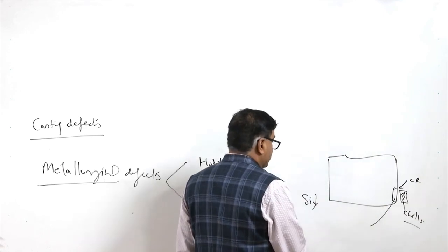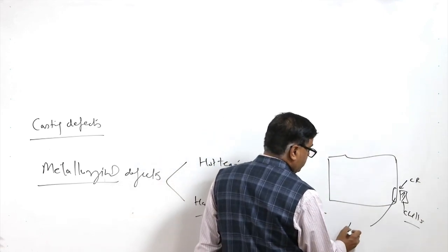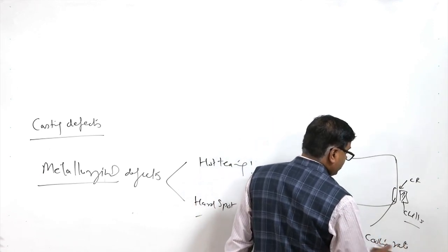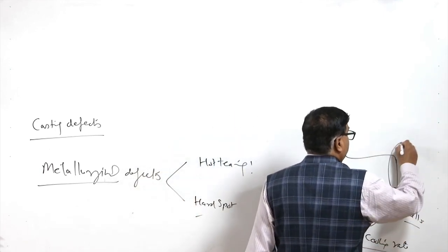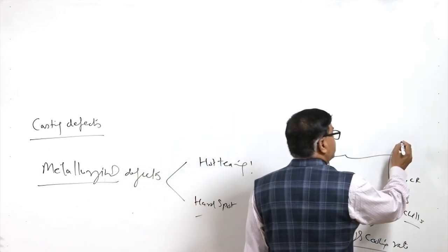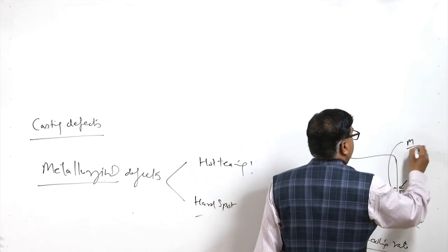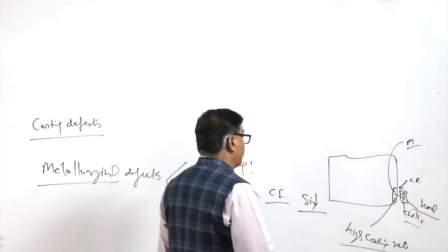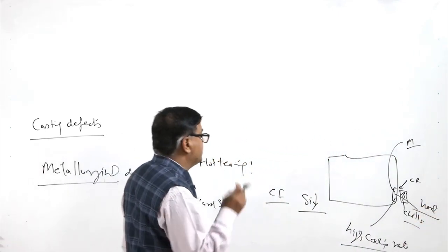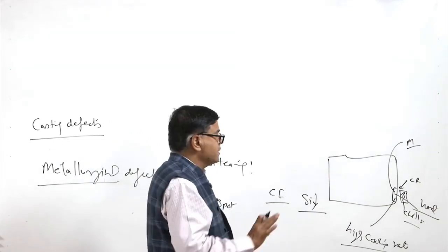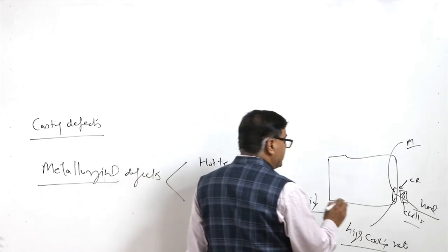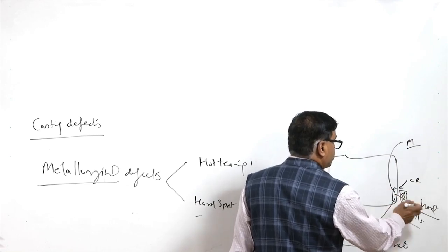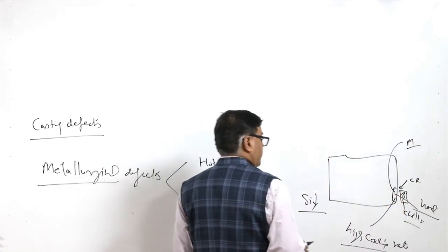In cast iron castings having low silicon content, if a high cooling rate is experienced by the surface, then instead of graphitization, this causes martensitic transformation. So, a very hard region is formed in the areas where the chills are applied for achieving directional solidification, and these increased cooling rates sometimes lead to the formation of martensite near the surface, which leads to the formation of hard spots.